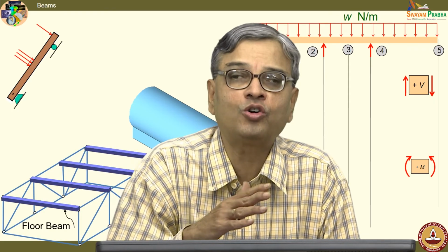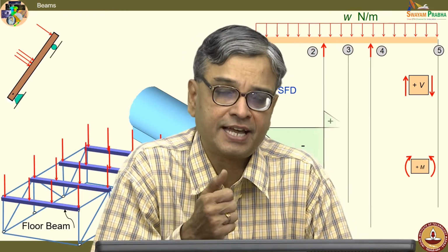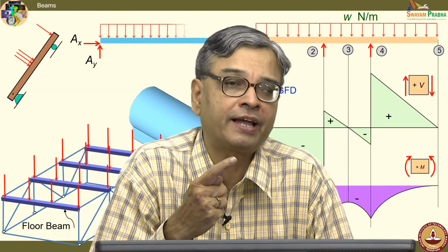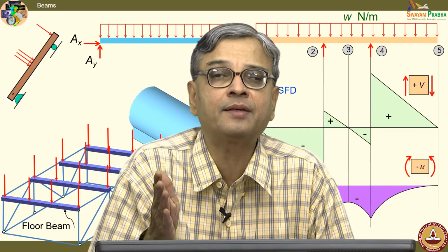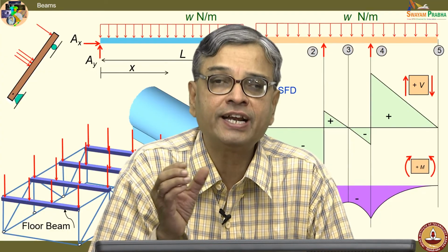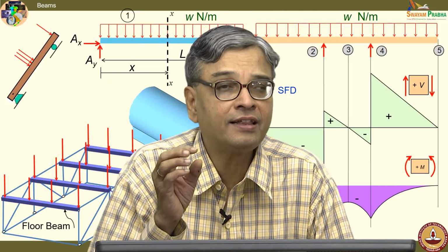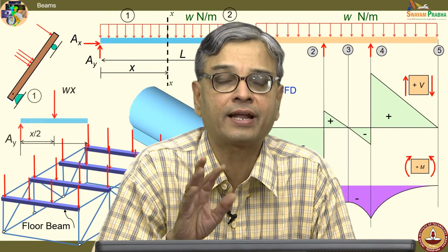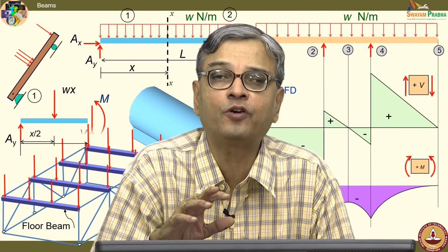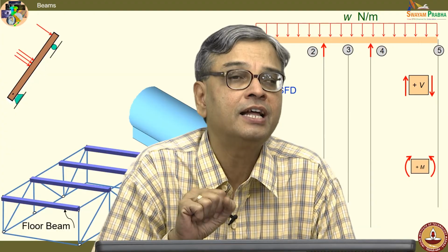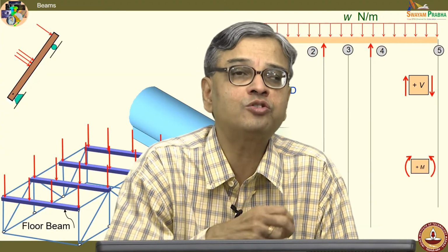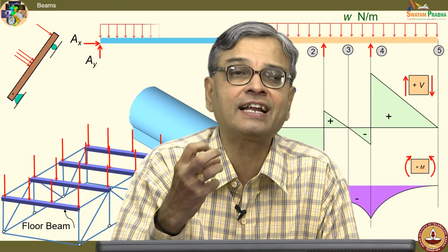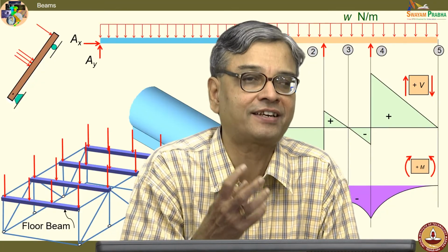See, you are learning the course for the first time, where you are learning the drawing of shear force and bending moment diagram, you should always cut an imaginary section, isolate the free body, calculate the bending moment and shear force using the free body. That is what I would recommend, and you would also be given credit for it in your final answer scripts. But nevertheless, you must also develop certain quick methods to verify, at least at selected points, whether your answer is correct.